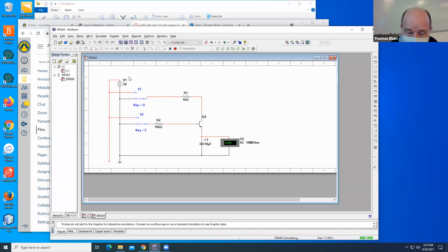And we can see in the hold state that voltage slowly changing. It's changing, but that's relatively slow, and in computer times, that's a slow change, but it is changing. And the significance of that is that the resistance is not infinite of this transistor in the off state. There's the resistance of the transistor in the off state, and then there are other things that are attached.